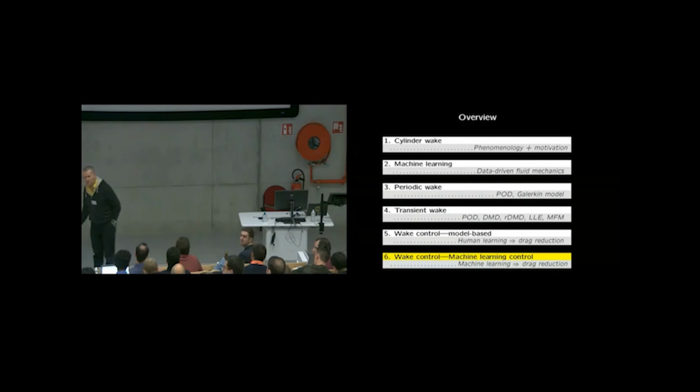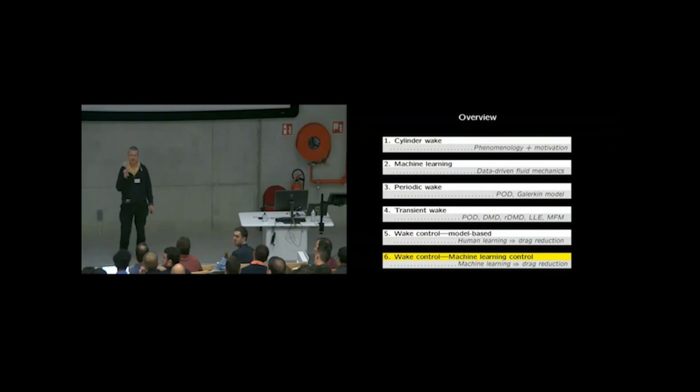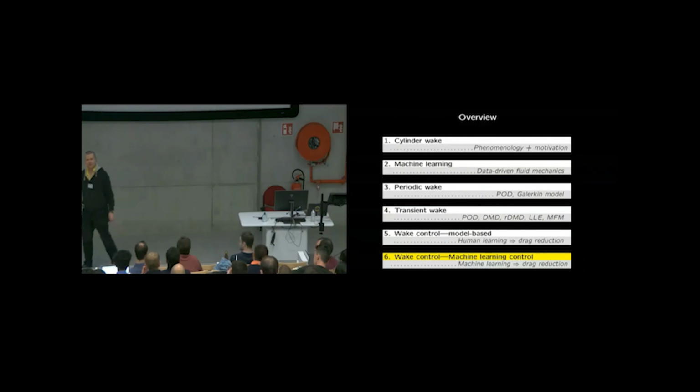Well, what you do, good question. So first you update the kinematics. You take the controlled flow, you take the POD of the controlled flow, then you put the changed POD modes, do another Galerkin projection. So you also change your dynamical system, and then you do the control again until you hit another plateau.